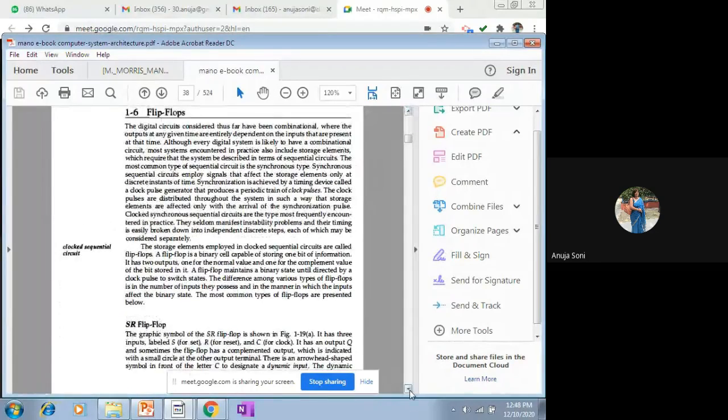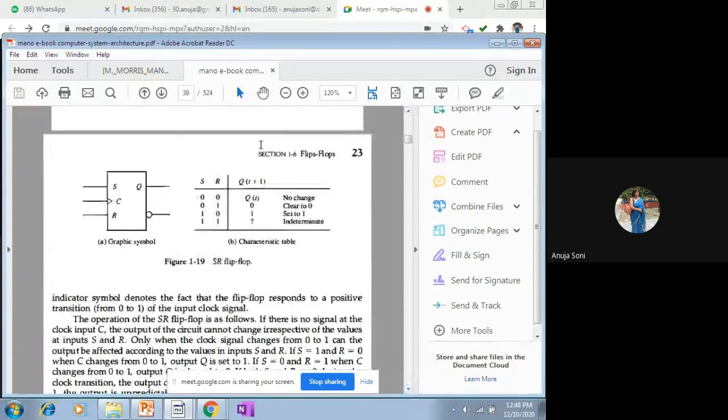SR flip flop के case में we are studying its output value generated at t+1th timing signal कि ये कैसे बिहेव करेगा, ये जो नेक्स्ट आउटपुट जनरेट होगा उसका बिहेवियर कैसे डिटरमिन होगा. It will be determined by the specific type of input combination. Is that clear now? And whenever value of SR is 1 1, in that case it is not predetermined, it is not fixed, behavior is not fixed, because it randomly works. Sometimes it generates the value as 0, sometimes it generates value 1.